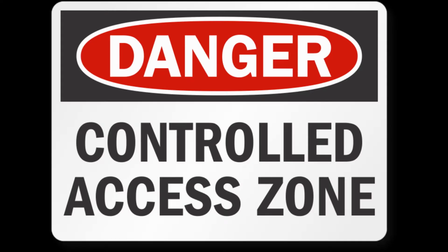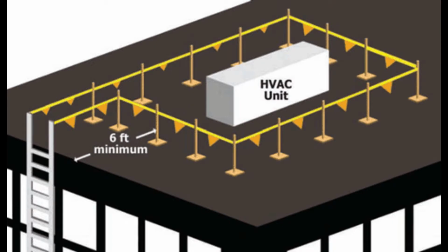Controlled access zones, CAZ. Controlled access zones are areas in which certain work may take place without the use of guardrail systems, personal fall arrest systems, or safety net systems. Access to such zones must be controlled. The locations of CAZ must be identified and classified as controlled access zones. Controlled access zones shall meet the following requirements.